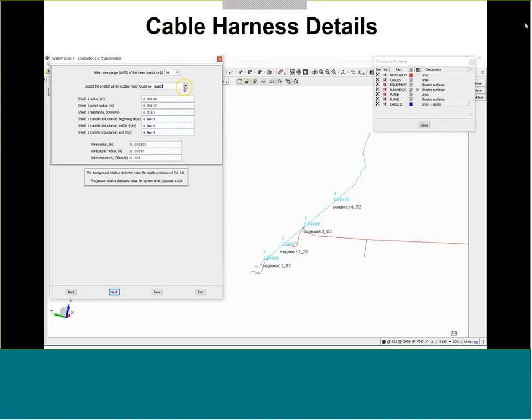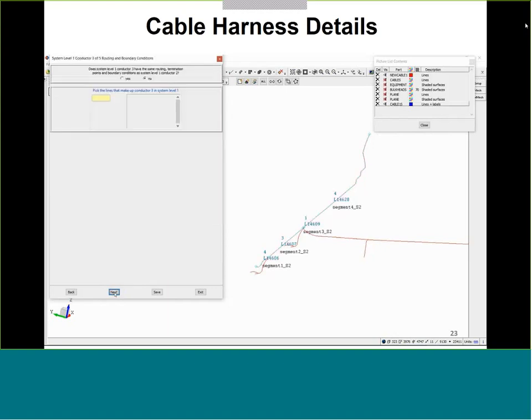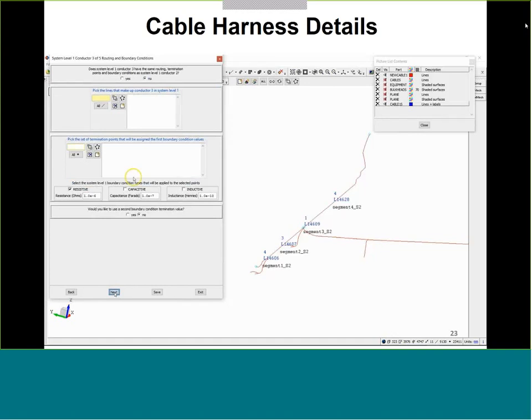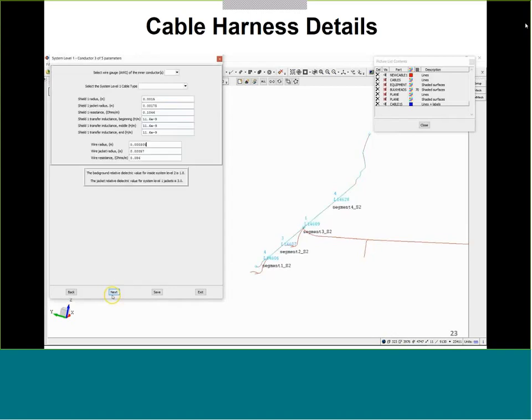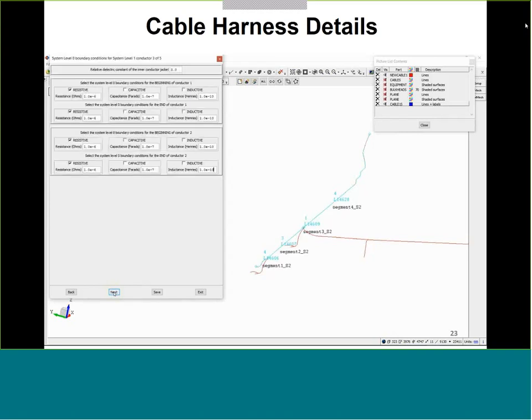At least it gets you a start for engineering. If you're using some strange cables, strange overbraid, you could do that measurement and just update it in the software. But if you're not sure, the values are preloaded. So having this cable database is a huge time saver. So in this case, first we did a quad, now we're doing a TSP. And so basically we're telling the software the routing is the same, but the conductor type is going to be different. So this case we're going to put maybe a power cable as a single line.